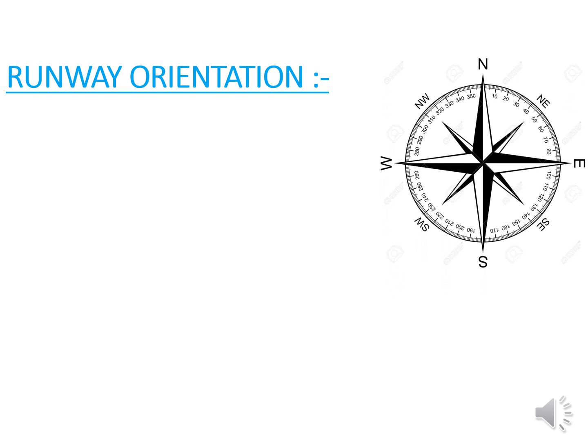Let's start. Before getting into the circuit pattern, you should know about runway orientation marking. The runway is normally used for intended takeoff and landing of aircraft. All the runway orientation is taken in reference to magnetic north, that is QFU. It's in Q codes, the magnetic orientation of the runway. To make the runway, wind component is a very important factor. The prevailing wind at that location is what the runway is made according to.